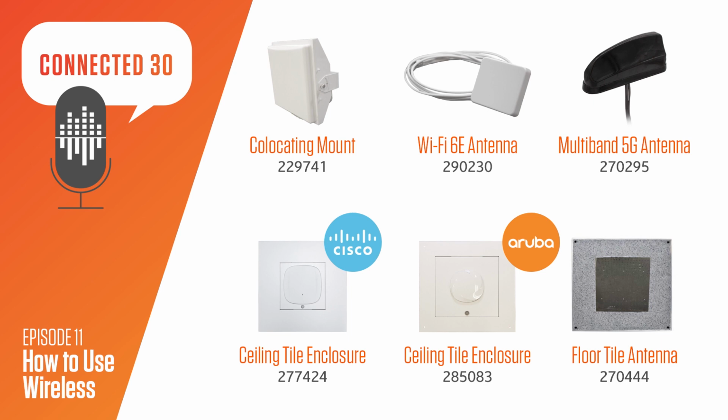And this is indoors, so you have to use internal antennas. Now, these power levels aren't high enough to interfere with what's currently operating in these frequency bands, or these incumbents. So there's no issue where you would need AFC. Now, a dBm, okay, that's a Dennis Burrell milliwatt. Yeah, if you want to call it that, but no, it's actually a dB per milliwatt.